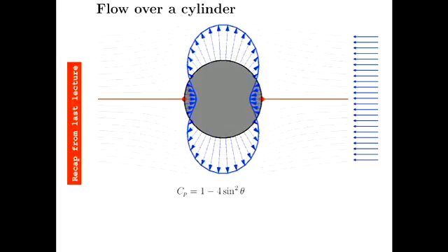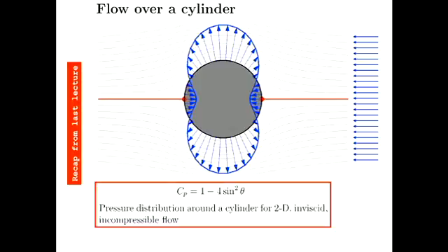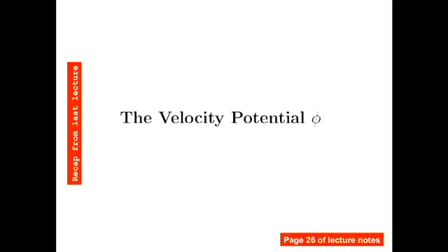So that's a bit of a detour, but the pressure coefficient is along similar lines. It's a dimensionless quantity that should be applicable regardless of the flow velocity or the type of fluid. So then right at the end of Tuesday's lecture, I introduced this concept of the velocity potential, which maybe in hindsight was a bit of a silly thing to do when I only had a few minutes left.